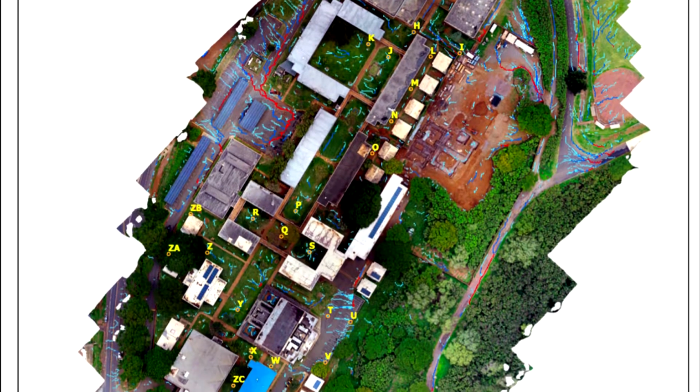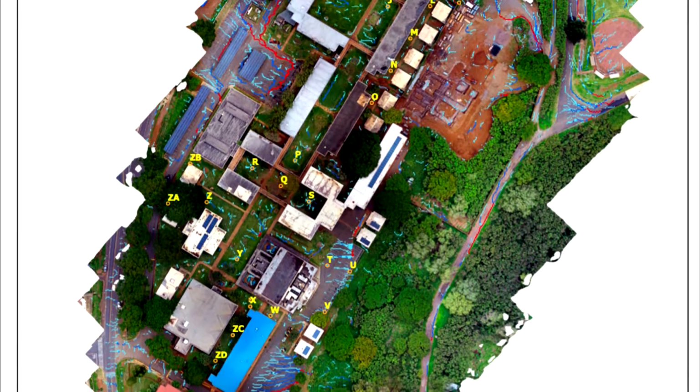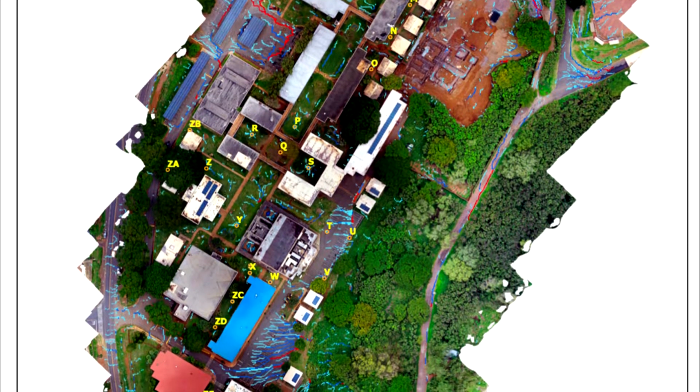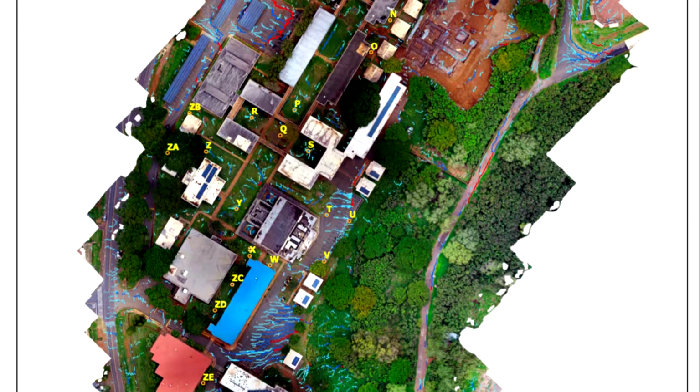So for our third map, we used ArcGIS Pro, and we used a drone map which was given to us. We plotted the storm drains in order to get a better understanding of, or to see if the storm drains are actually placed in the spots where there are a high concentration of flooding or low concentration of flooding. And the map can also show us where we could technically put more storm drains, so it would lessen the flooding on campus.